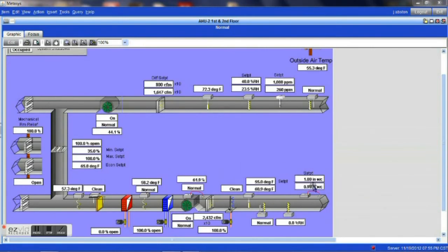If we overshoot our static pressure set point when a lot of the rooms go unoccupied, or if they become satisfied with the airflow that they're receiving, the drive will then back down until our pressure reaches its set point level again.